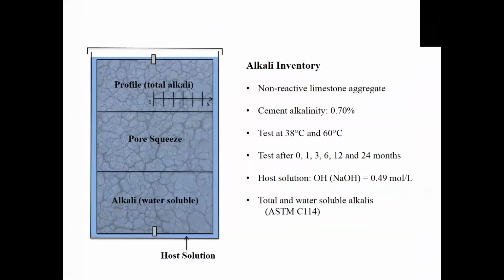What we do know is the alkalis haven't changed that much, but in the host solution, the hydroxyl ion concentration has dropped, but the alkali concentration, the sodium potassium, has remained reasonably stable, which indicates that surrounding solution is carbonating, and it perhaps carbonates to a small extent every time we take the sample out and measure it.